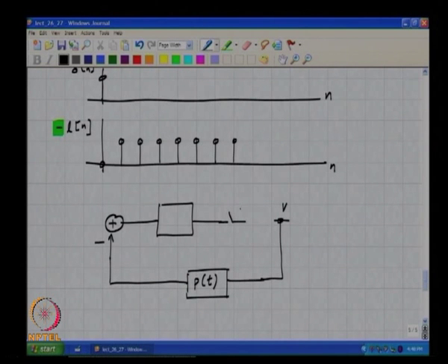right, and inject an impulse, we should see, if this was claimed to be a first order modulator, when I broke the loop here at E and apply a discrete time impulse on one side, the sequence which comes back at the other end must be exactly u of n minus 1. Is this clear?